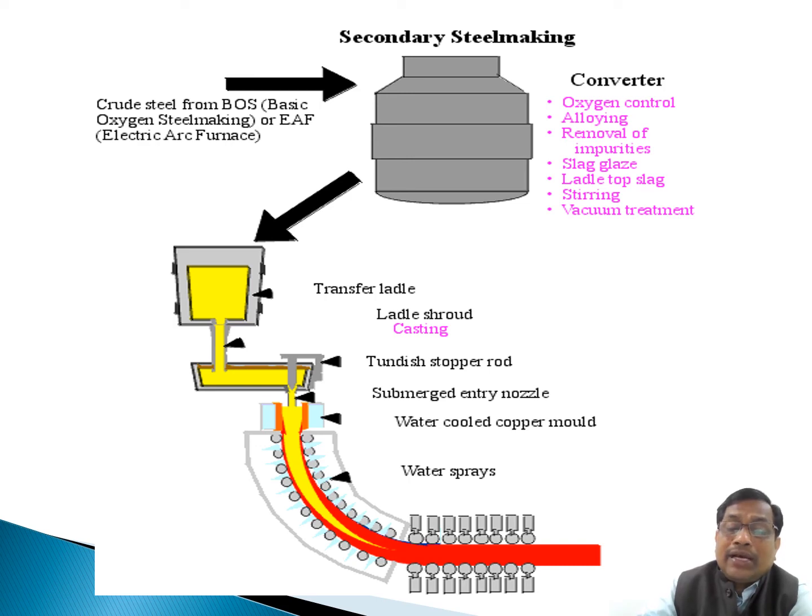And here you can mark the skin thickness is increasing, and at this point generally the cross section becomes solidified. Once it is solidified, it is coming out from the secondary cooling system, and again it is produced in a horizontal way. Now the bar is coming in a horizontal way. Here a cutting torch will be there, and this cutting torch is trying to cut the material.